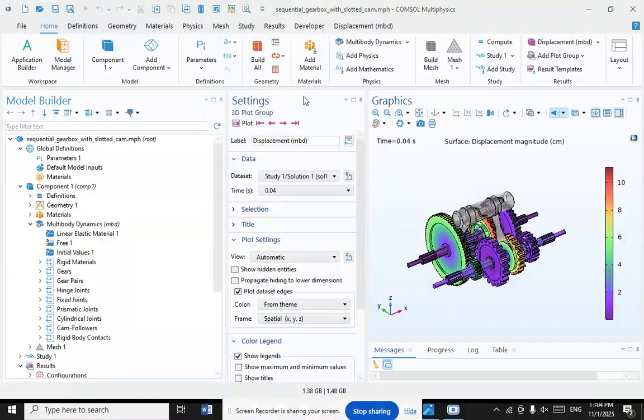Even after the car has stopped, a mechanism is needed to stop the input shaft, such as using the synchronizer ring for fifth gear. However, some vehicles do employ a synchromesh system for the reverse gear, thus preventing possible crunching if reverse gear is selected while the input shaft is still spinning.